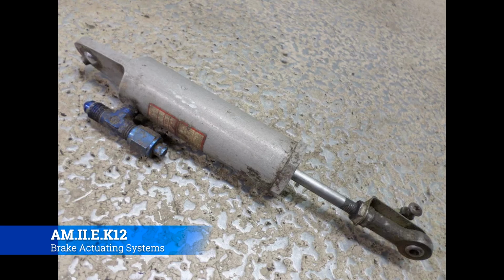Notice that it's really simple. It's just simply a little kind of actuating cylinder. Nothing really over the top. Now, another thing to take away is look at the travel that bell crank has in and out of the cylinder. When you look at that compared to the distance the brake pad has to travel, which is probably about a quarter of an inch, it's not really that much at all.